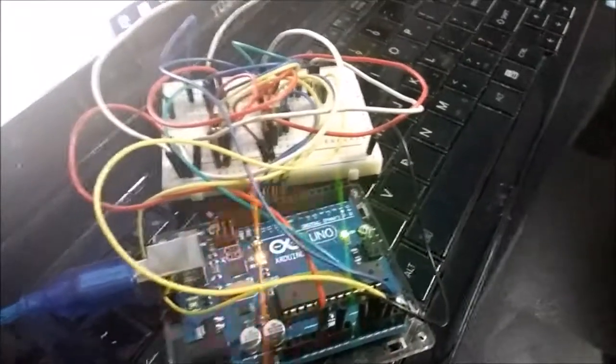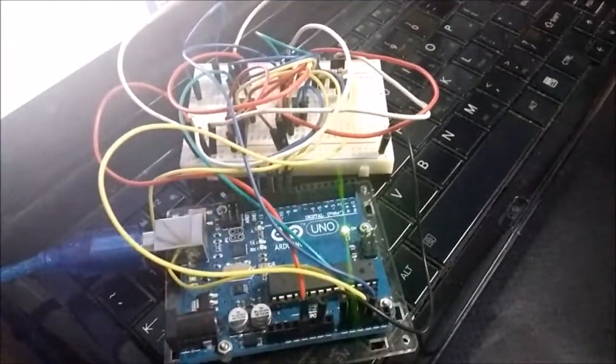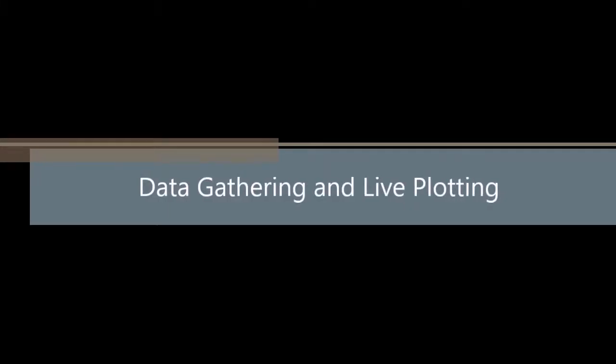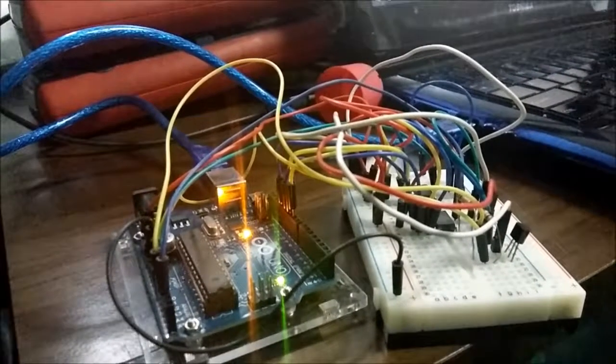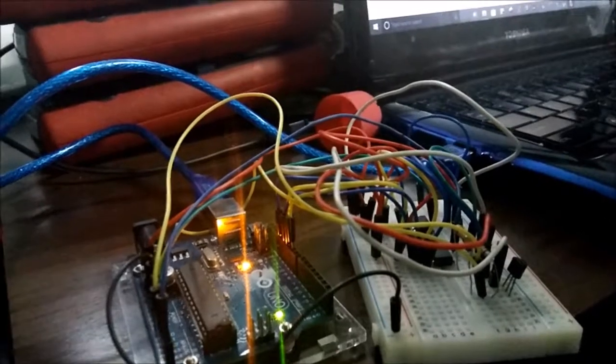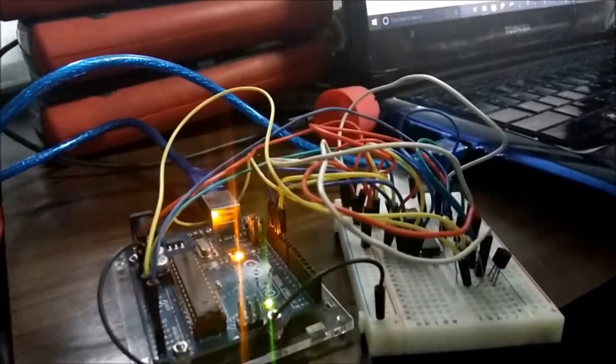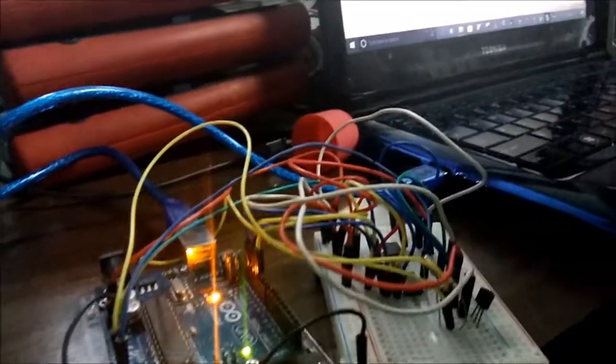So now, we'll discuss how the live plotting of Python works and how it communicates with the Arduino-implemented curve tracer for the data gathering. For our data gathering, we've implemented a curve tracer in Arduino as a tool for live plotting. The curve tracer can generate and display a family of curves of collector current versus collector-to-emitter voltage, or VCE, for various values of base current, or IB.